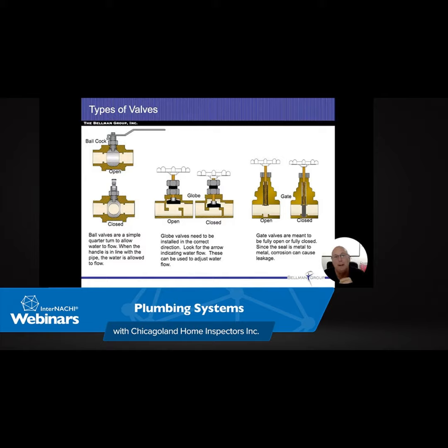And what's kind of weird is that every frost-free water spigot is a variation of a globe valve like this. So where that black piece is, that's more of a rubber washer that's flexible and bendable when it comes in here. And as I open it up, now this water is supposed to be flowing from left to right as we're looking at these diagrams.